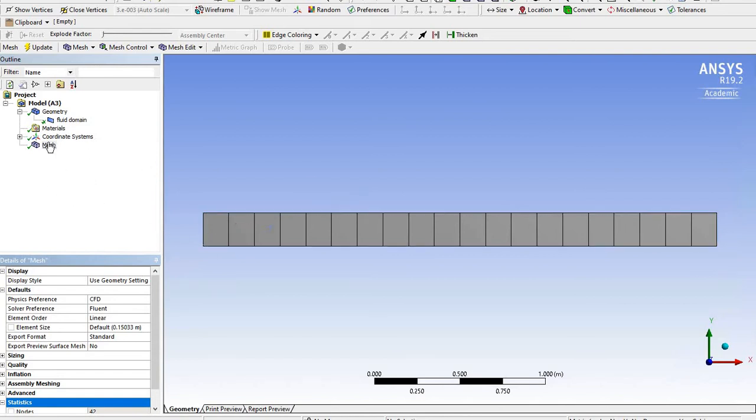So because we will lose the resistance calculation from the wall to the middle, there will be low velocity near the wall, high velocity near the middle. But if it's one cell, we're not going to be able to see that. So what we need to do is increase the number of elements near the wall.